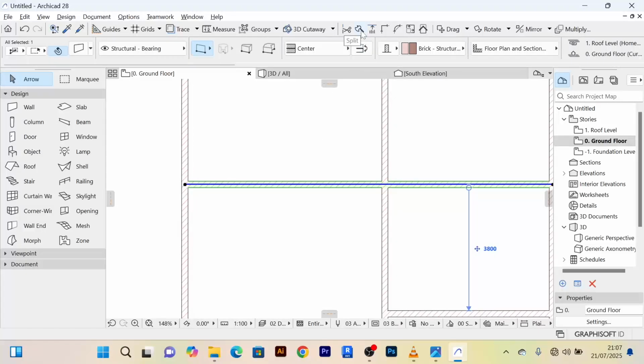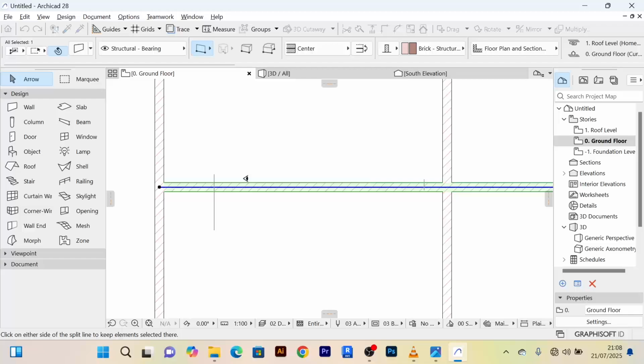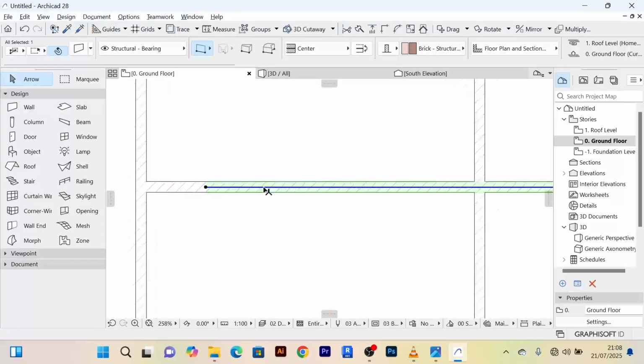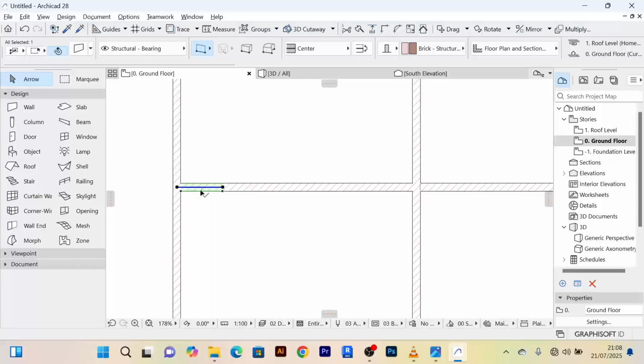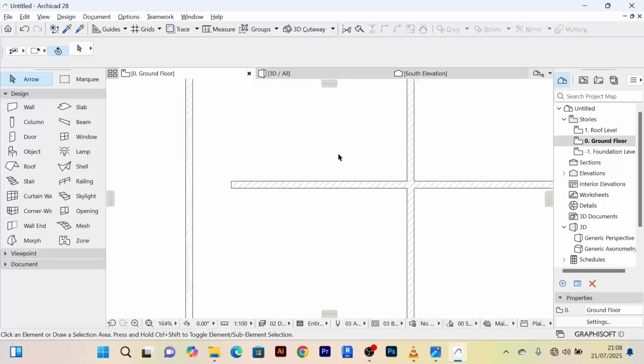So it is this axe that you see here. It can help you to split anything anywhere. So when I click on this, I can click on the part I want to split. I can just click on like this, then it will show you there's an eye. This eye will indicate where you want to preserve the wall. So when I click here, it will show me this one is being preserved and this one can be taken off, just like that.